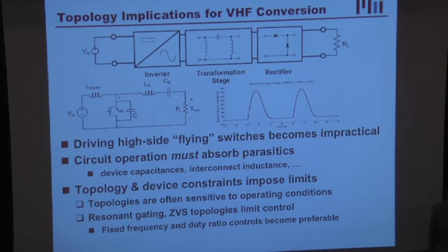Lastly, I should point out, and I should note that this is an example, this is actually a classical RF amplifier topology that illustrates these two constraints. First of all, when you turn this transistor off, the device capacitance rings with the output to generate zero voltage switching. This is a so-called Class E inverter. So I can turn on the device at zero voltage, and so not only do I have a ground reference switch, I have the parasitic capacitance of the device absorbed.